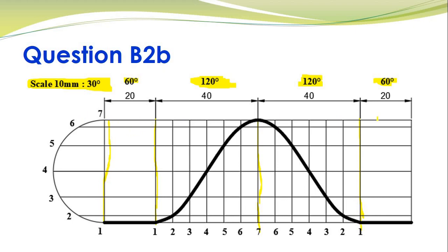So then for simple harmonic motion, we divide the stroke semicircle into 6 equal parts, right? Very important. For simple harmonic motion, we don't divide the stroke into 6 equal parts, but we divide the stroke circle, or basically this semicircle, into 6 equal parts. And in MM101 you already know how to do that division.